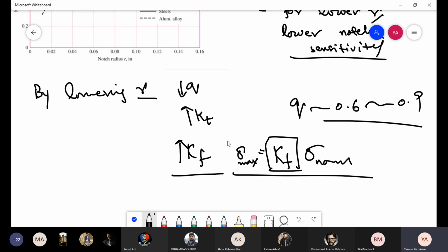Because if we use it with the strength, a problem occurs when we go for combined loading, for example with torsion involved, and for torsion you have a different stress concentration factor. Different types of loading have different stress concentration factors, so you don't have one factor you can divide the strength value with. So it is better to take care of it in terms of stresses, and we will do that in this course.